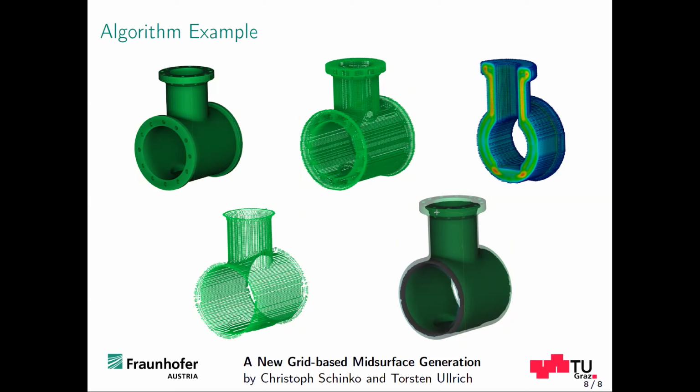However, what you can also make out is that we have shrinkage problems at the object boundaries. This can be seen at the mounting surface on the top, where the mid-surface is slightly smaller than one would expect it to be. But depending on the simulation use case, this may not even present a limitation. However, we are investigating this in future work.